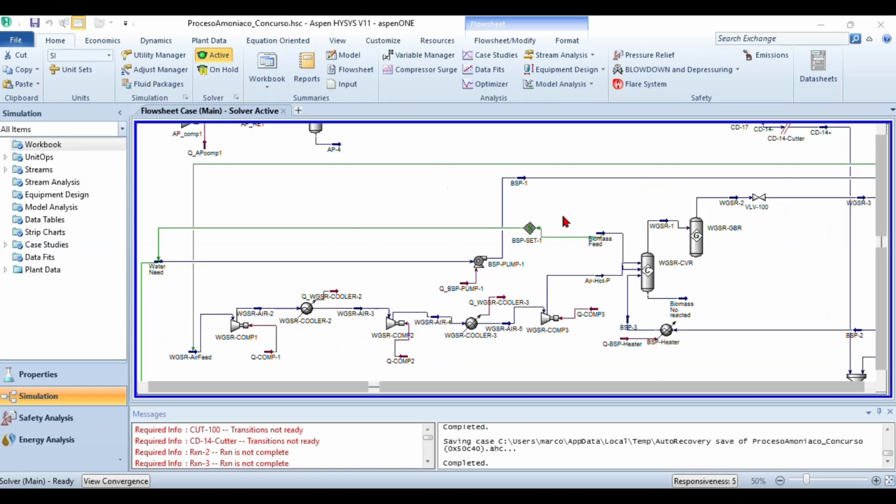We use the Peng-Robinson equation of state to accurately predict phase behavior at the supercritical condition of water, 240 bars and 700 Celsius degrees. The gasification is simulated in a two-stage sequence. In the first, the reactor handles the primary elemental thermal decomposition, and the second reactor calculates the chemical equilibrium where we optimize the water-gas reaction to maximize hydrogen selectivity.